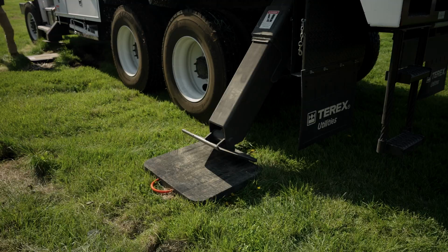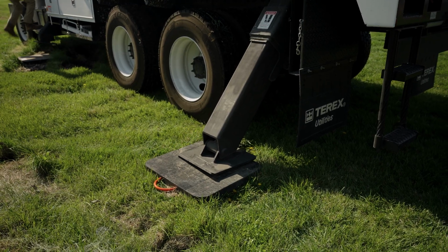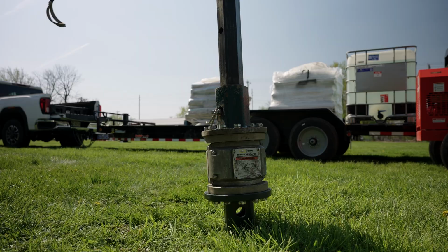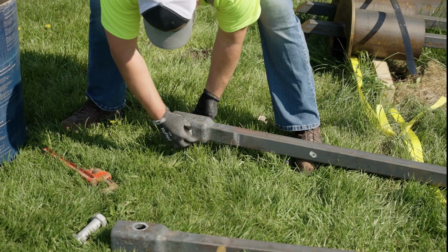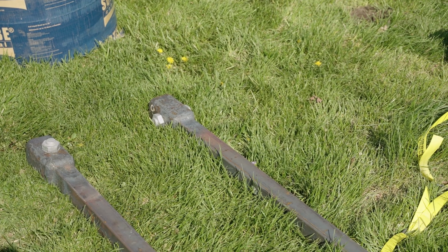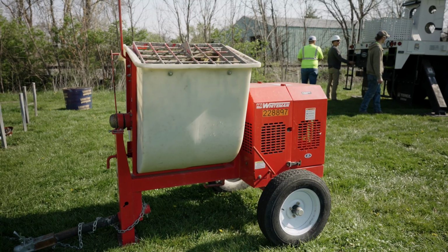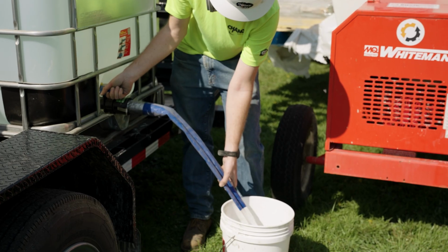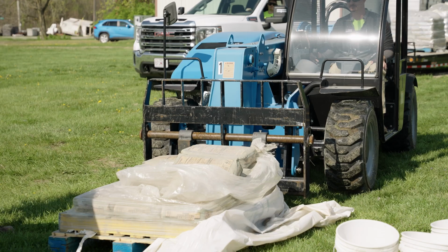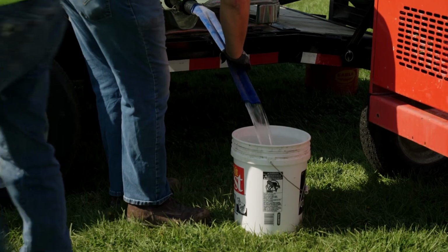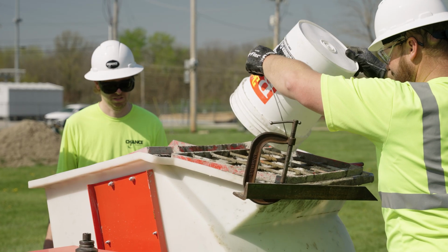GDP is installed with common construction equipment and tooling used to install conventional helical piles. The 5-foot section lengths allow for installation in low overhead, limited access sites. Grout should be mixed using equipment capable of providing a steady supply at the required level of production.